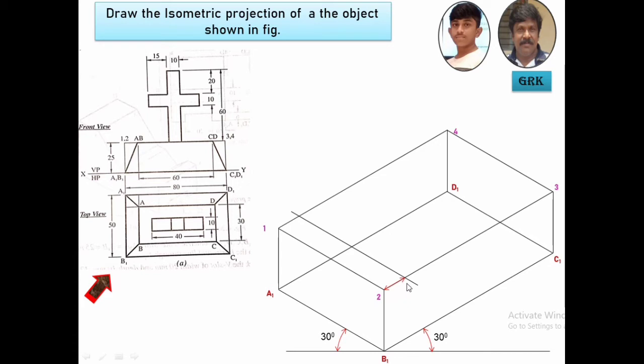All these lines are drawn only for construction purposes. Afterwards you can erase them or leave them there itself. Now measure this right side, that's also equal to 10 mm. Mark it on the right-hand side. This is the constructional procedure to get A, B, C, D. Now measure this.